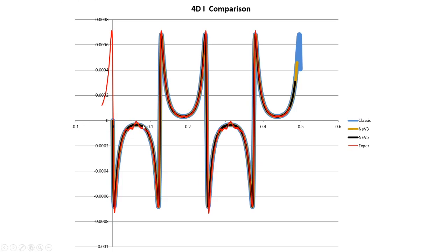Now here's an interesting thing, and we're going to go research this later on. Our ripple, there's our 45 microvolts of ripple right there. Okay, you don't see it on this. You only see it here. You can see noise here. You can see the ripple here. This is where the magnet is actually over the wire of the D. Here, this is where the magnet's over the backside where there is no wire loop of the D. And this shows that we have coupling from the magnet to the wire. That's the only thing it could be. So this shows there's something, a very small effect that we're going to take a look at later. I'm pretty sure this is due to the vibration of the experiment, but I'd like to understand how that vibration correlates to this ripple.